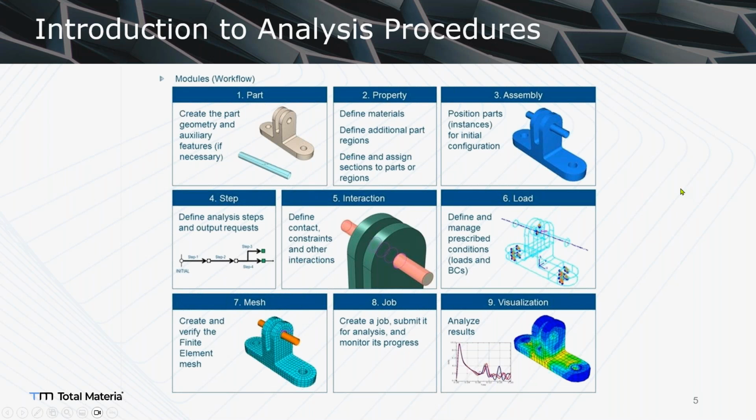All these sections need to be constrained from different perspectives. With material characterization, there is a common saying in FEA work: garbage in, garbage out. When you go for garbage input, your result will also be garbage. So you need to select really good inputs, and that includes the material.